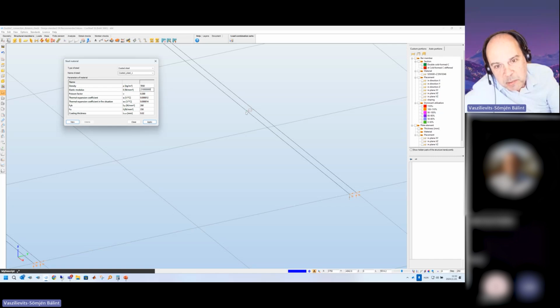And then I define this beam with the right boundary conditions at the desired location. When I run the analysis and look at the connectors, if I use the special profiles, I can easily select with the nice auto selection functionality only these link elements, and then I can see the internal forces on them, because in that model they are acting as normal beam elements, and all the internal forces are visible. This is maybe a bit painful, but at least it's possible.